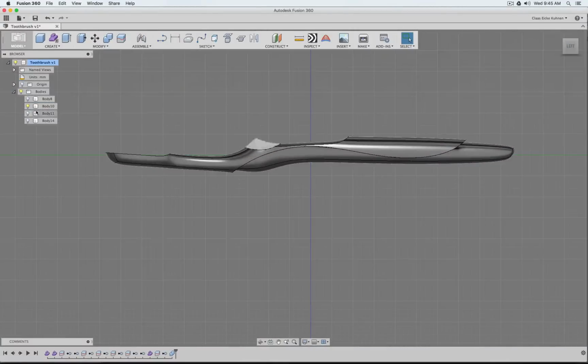And you see inside the body lister, it's only one part now. Before those were two objects. So this combine actually combines the two objects together and hides what's selected blue, because essentially you might just want to have this as an end result, so one object.